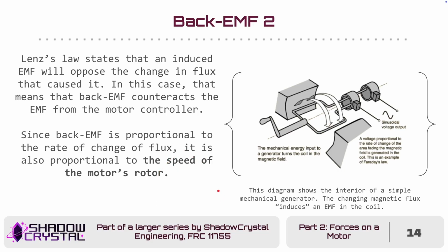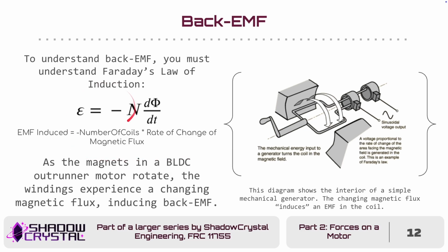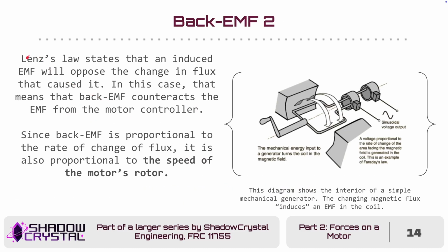Now, it's worth noting that back EMF opposes electromotive force exhibited by the controller of your motor because of Lenz's law. In other words, an induced EMF, like the one in back EMF, will oppose the change in flux that caused it. So, for example, the speed of your motor is inducing the change in flux, so the back EMF is going to try to slow down your motor to counteract that change in flux.